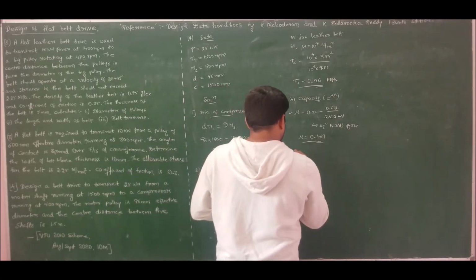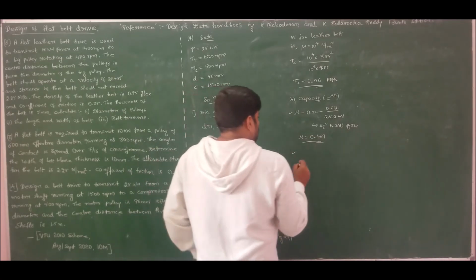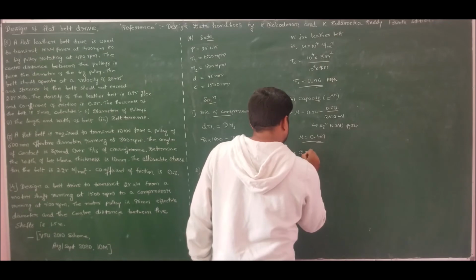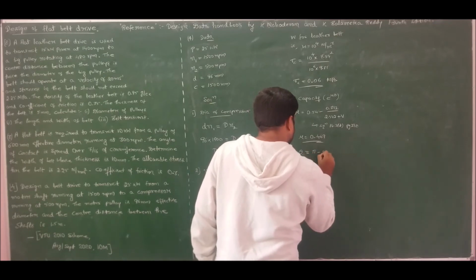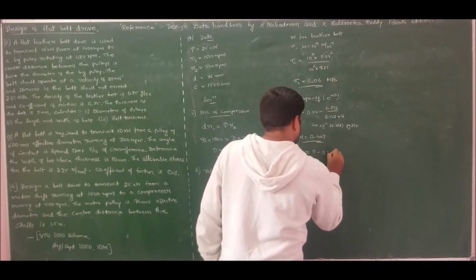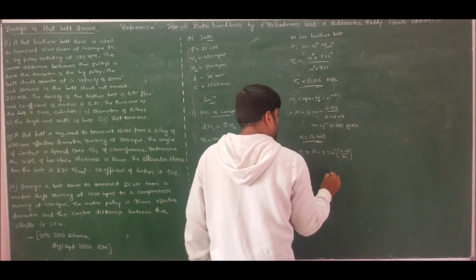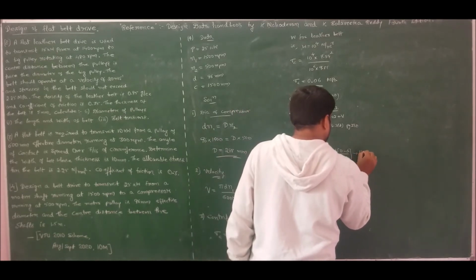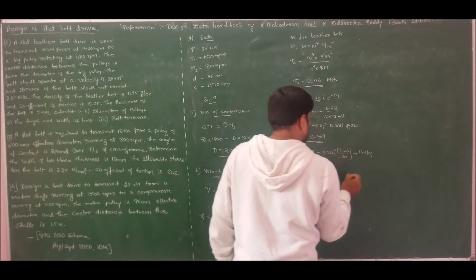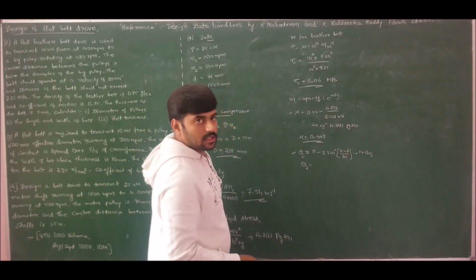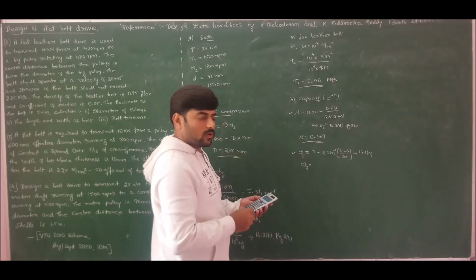So now let us calculate both theta s and theta l. Theta s is equal to pi minus 2 times sin inverse of D minus d by 2c. This is equation 14.1a. A very important note is that your calculator should be in radian mode while solving.